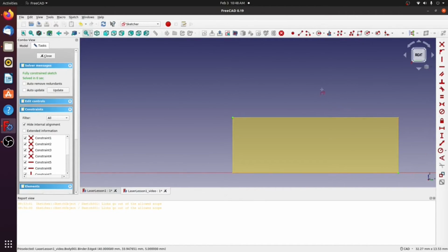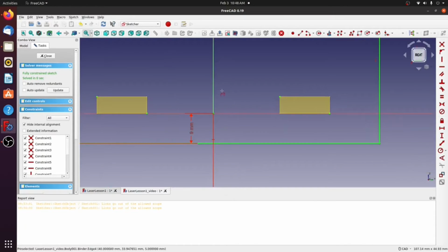Highlight this point. And now I have all the geometry that I need to create perfect slots inside of this side piece. We'll escape. There you go. And we're just going to take our little square tool and we're going to start drawing onto that geometry. There we go. Now you can see that it has automatically constrained these corners here with a coincident constraint. It basically is guessing that we want to keep these 2 points exactly on top of each other, and it's filling it in for us.